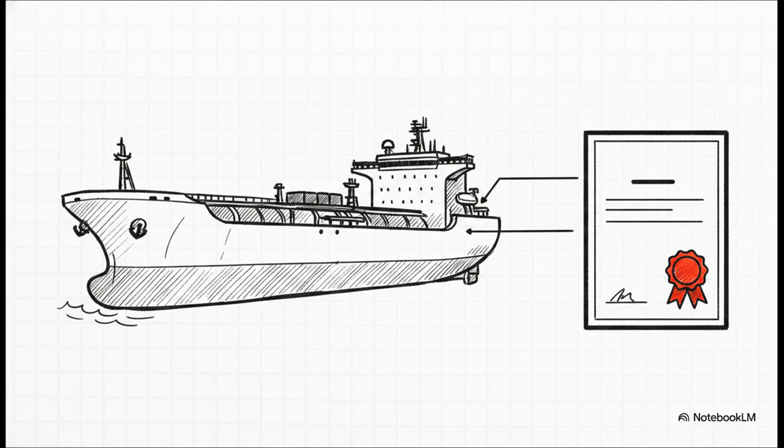Now, what's really interesting about this slide is how the Ex Equipment Register is actually framed. It's not just about electricity and preventing sparks anymore. It's tied directly to the vessel's marine survivability. Your feeder data has to include hull and buoyancy classification documents. It has to reference the cargo tank and ballast systems. And you need those DNV or ABS sign-offs for that critical turret and process interface. The electrical safety documentation is, for all intents and purposes, married to the marine classification.